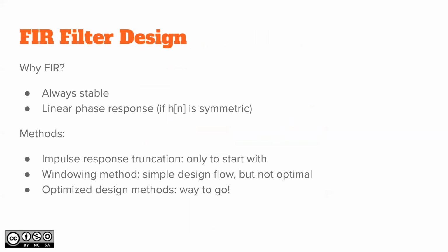Okay, let's start from the FIR filter design. There are two good reasons to use FIR filters. Basically, if you don't need linear phase response, then usually you don't need FIR because an FIR filter requires more calculations.